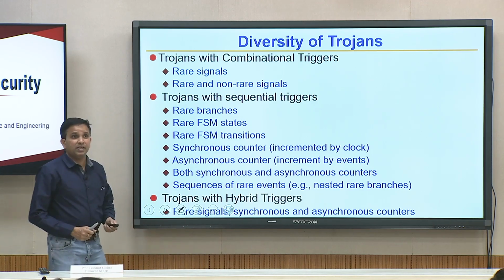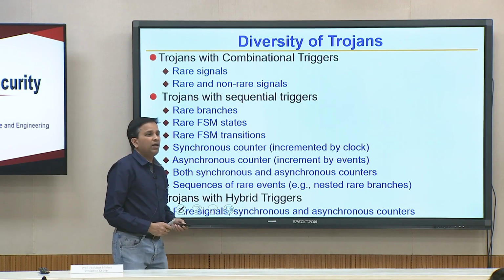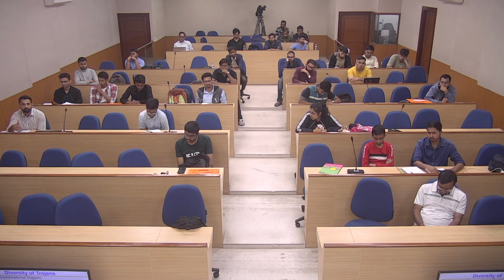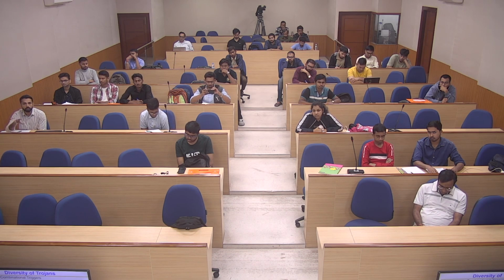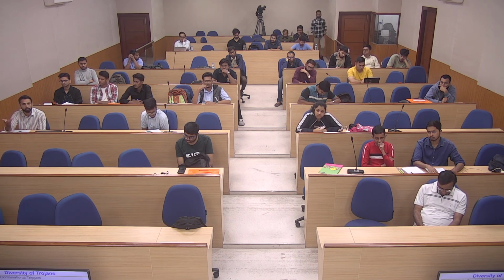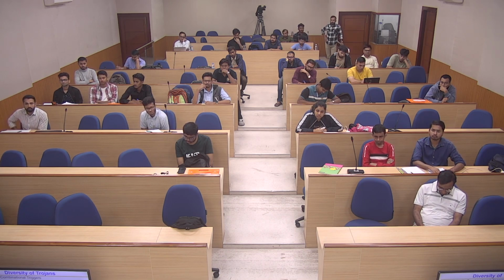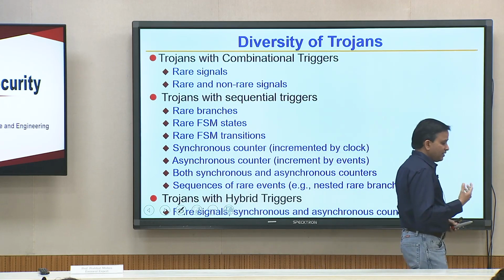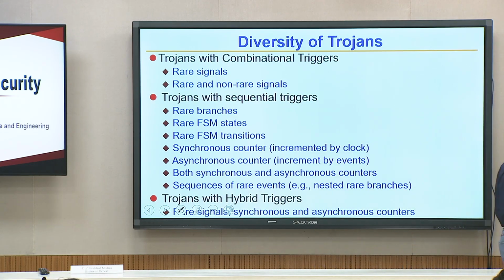Excuse me. Yes, please. One doubt, sir. Like we have spoken about the triggers, which can be combinational or sequential circuits, but in both they trigger a particular payload. So the malicious circuit is the payload itself, and that has to be integrated within the hardware itself, or can it be a software based payload which is the malicious part? Right, interesting question. So, the question is trigger could be combinational and sequential, but the payload, should it be integrated in the design itself or it can work with somebody else.